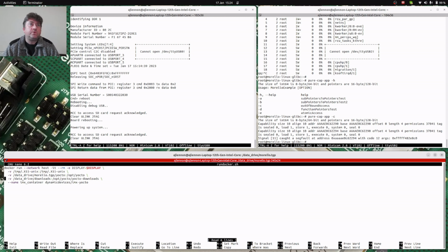Now that's no good for us because there's a huge amount of building that needs to go on with Yocto, and we don't want to have to do that every time. So what we do is we break out of the container so that all of these build artifacts and the outputs of what we're doing are stored in a file system tree on the host operating system. So I bring up my container, do all the building, that all gets stored nice, neat and safe, take down the container, and I've still got everything, and I can build it up again and continue from where I left off. And that's really important because depending on your hardware system, Yocto can take many hours to do its build. It's doing a lot of work.